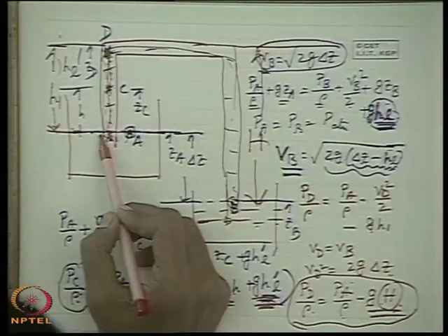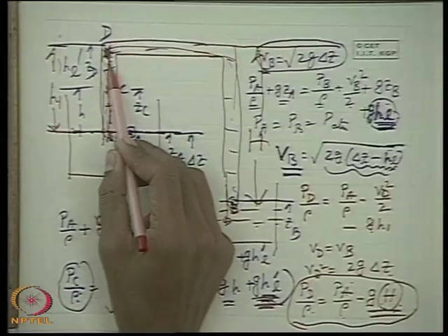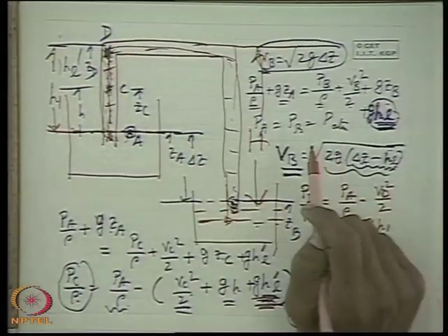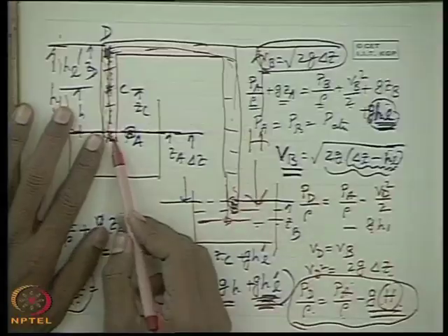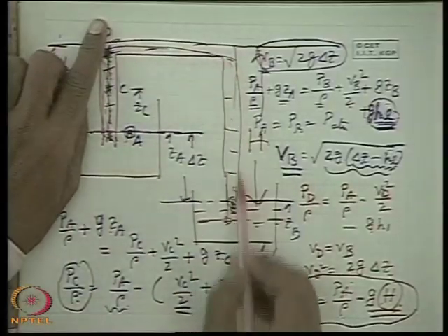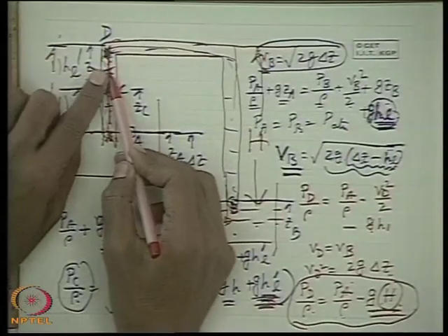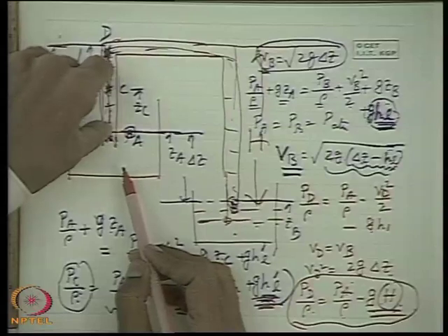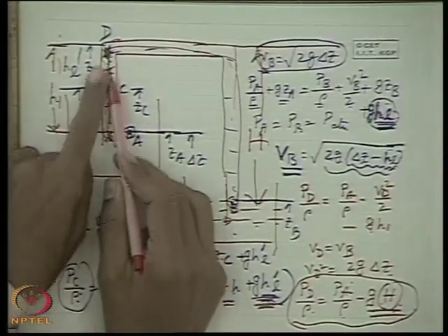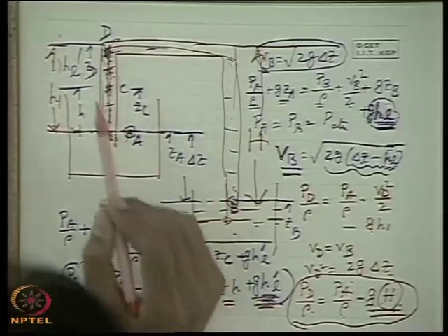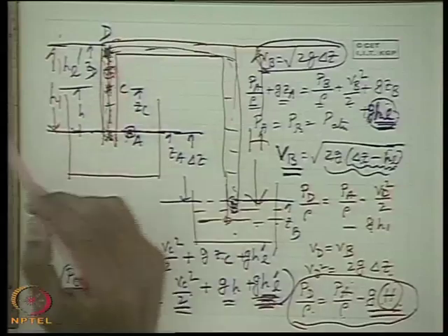Obviously, if you go on increasing the height, the vacuum pressure will keep increasing, and the pressure is going to be lower and lower. What is the restriction on the minimum pressure? Can you tell me? Physically it is alright, we can make a very high tube and make the flow possible. Theoretically, the pressure at any point as you go up will be lower than the atmospheric pressure by this potential head and the kinetic energy created. If we take a very small tube, the kinetic energy will be very high. So under all situations the physical definition is alright, but is there any limitation on the minimum pressure?